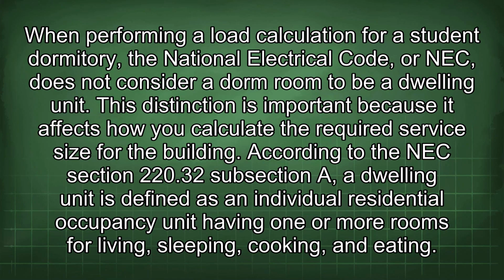When performing a load calculation for a student dormitory, the National Electrical Code, or NEC, does not consider a dorm room to be a dwelling unit. This distinction is important because it affects how you calculate the required service size for the building.